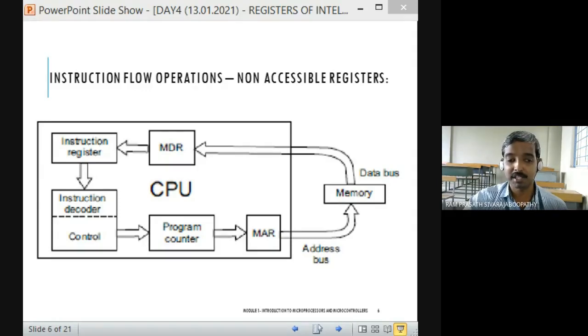So in the next memory, what should be there? Data should be there. So what is the first one? It is an instruction, 3E. What about 37? It is a data. An instruction contains what operation it has to do and the operand. Understand this well: in any instruction, what work to do and the data for it, both are mentioned. Clear? So 3E denotes we have to move a data to accumulator register. That's all. What about the data? 37. It is available in the next memory.